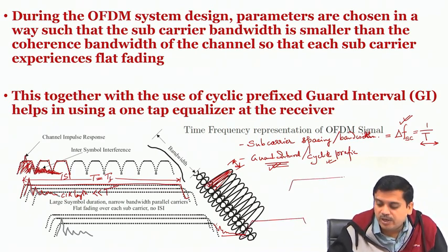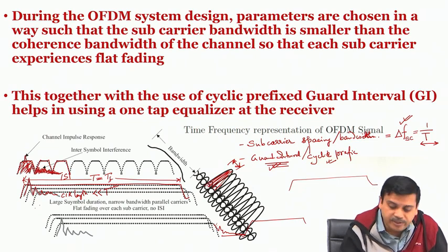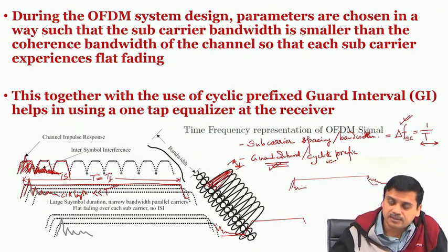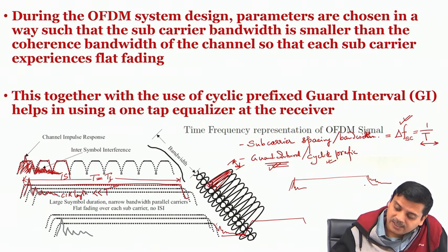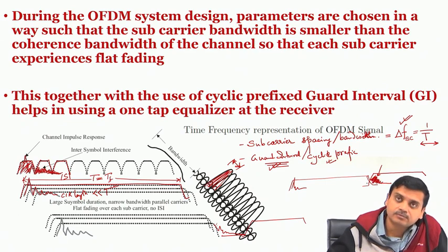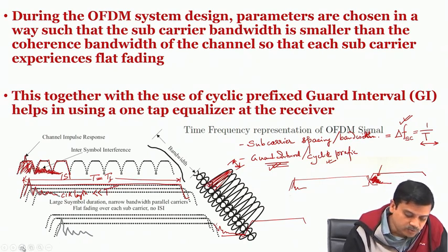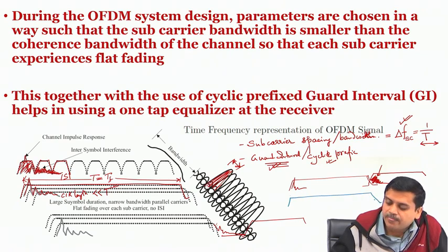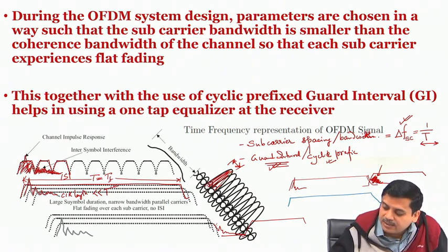So, basically this is one OFDM symbol, you have made it pretty large compared to the channel impulse response, this has already been done, but still because of the channel impulse response, the end will become something like this. Now, the next OFDM symbol is supposed to start from this point. So, there will be some amount of ISI present over here. Okay. To avoid that, what one can usually do is choose a design where, between the symbol duration and the next symbol, there is some guard interval.